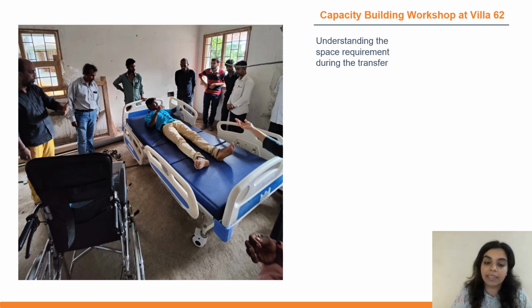And the electrician also looked into this and added the required points being 15 amp rather than 5 amp. We usually do not provide a lot of 15 amp provisions in rooms, but I think it's important that we at least leave provision for this to happen in future if anybody is in need of it.